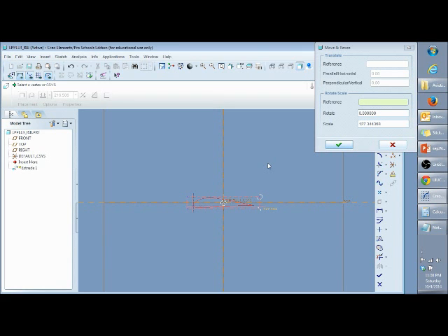Now you want to modify your scale here. Remember that 1-inch thing that we had used as the basis for the line? That comes into play in this step, because with that 1-inch scale, whatever scale you enter in here is what that translates to.